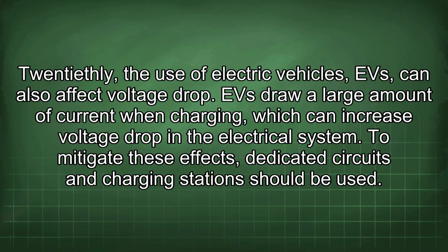20thly, the use of electric vehicles, EVs, can also affect voltage drop. EVs draw a large amount of current when charging, which can increase voltage drop in the electrical system. To mitigate these effects, dedicated circuits and charging stations should be used.